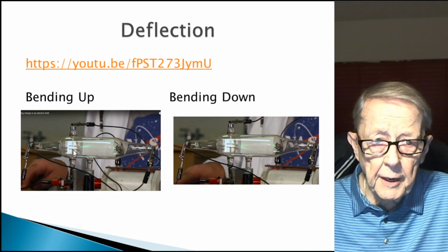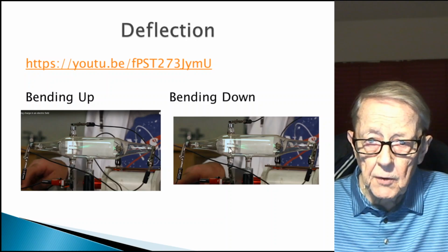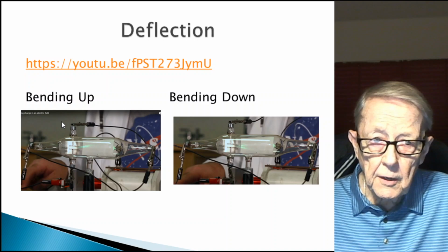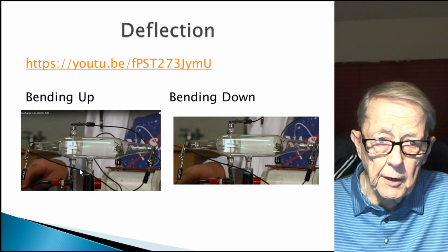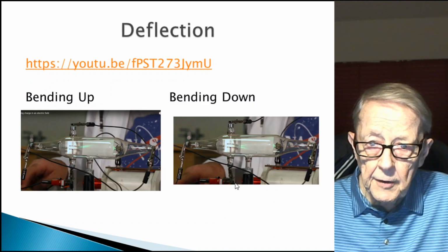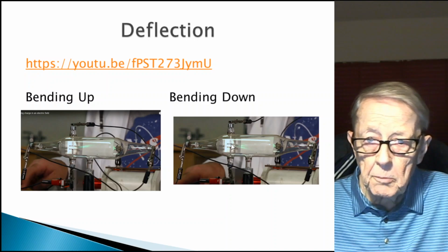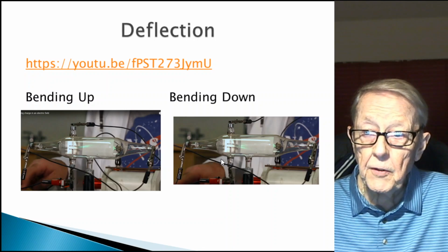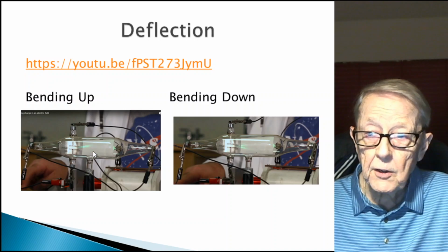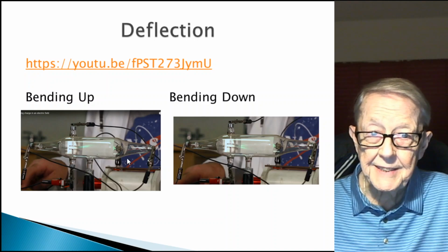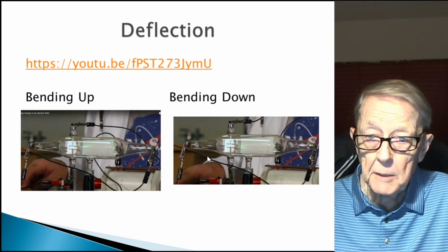And it's being bent by two plates inside here that are charged with a DC voltage, and this one is as well. All they did here was to reverse the polarity. Plus would be here, minus here would make it go up, plus down here on this terminal down here, and negative up here makes it go down. The odd thing is these aren't really two different things at all. You could just stand on your head, look at this one, and you have this picture. Physically, what's going on is the same thing. There's no difference between the two.